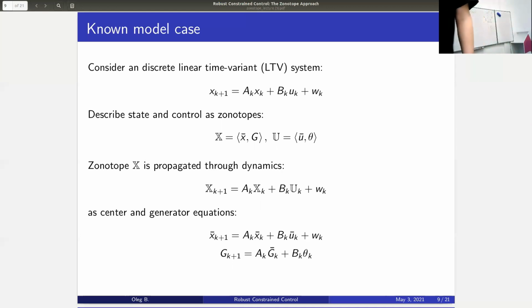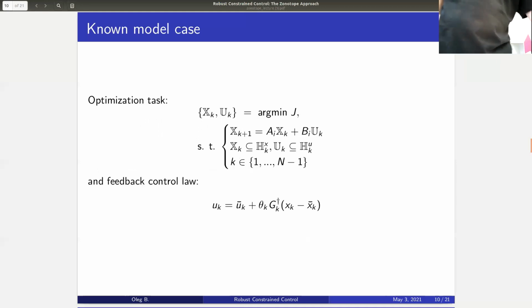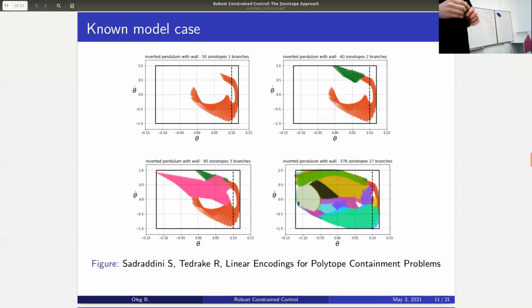If you allow me, just one other comment. When we go from just applying feed forward to computing feedback gains, what we also have is, first of all, some way to calculate or estimate stability, right? With feed forward, you cannot really estimate your stability.